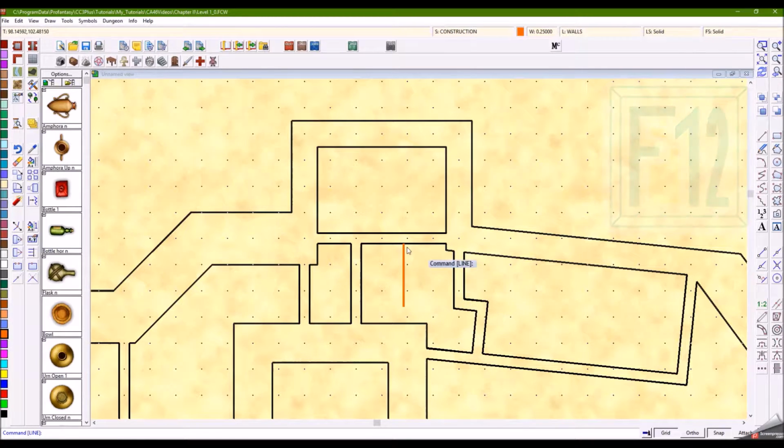Now when I use a tool at this point here, the selected entity can be the black line or the orange one. To avoid selecting the orange line, I use the half scale button and reduce this line. I can still get the midpoint with the intersection modifier.